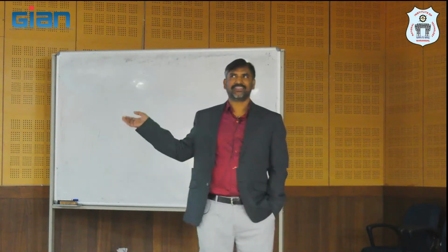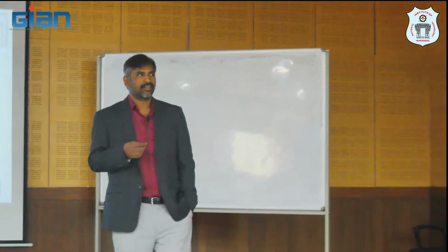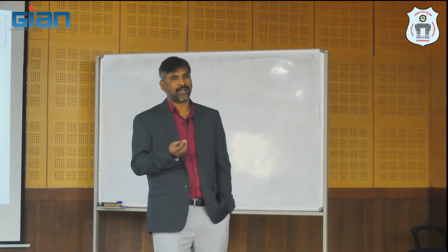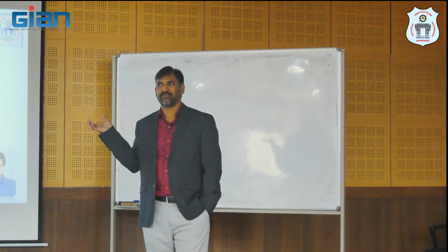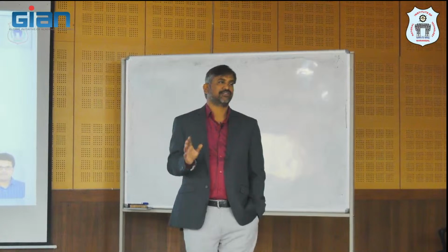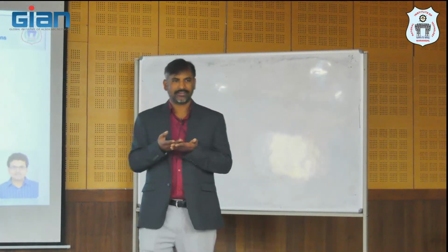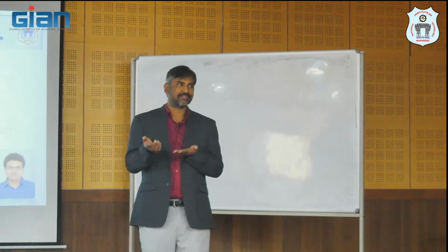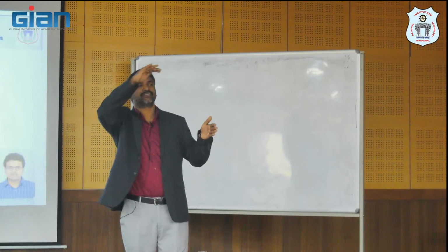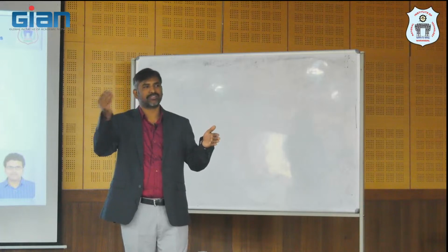And there are issues, as I said, right? If I use this device for a longer period, let's say 1 year or 2 years, and your film is prone to moisture, it may not produce the same response on day 1 and 365 days later. There are such issues. You should make a device which will stand for a longer period, a larger number of test cycles. Suppose it withstands, let's say, 10 lakh cycles without any degradation in the output signal and in the material property, then you can commercialize it.